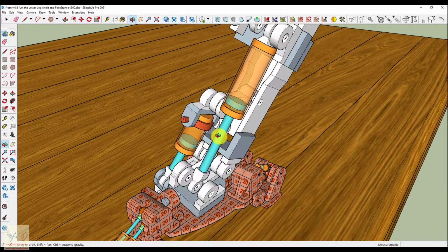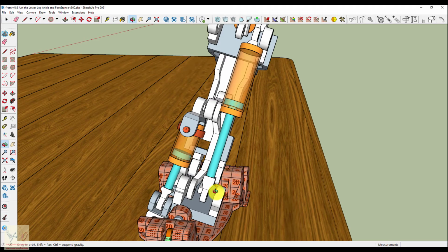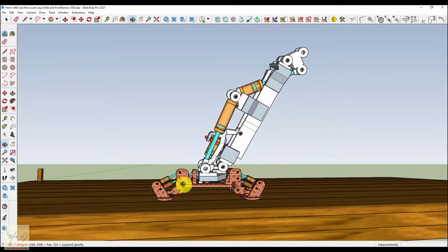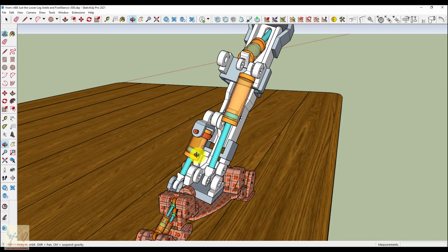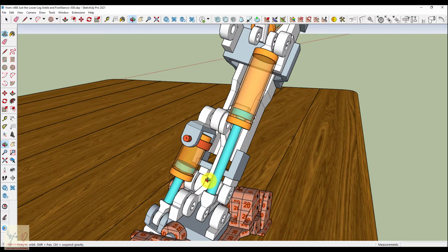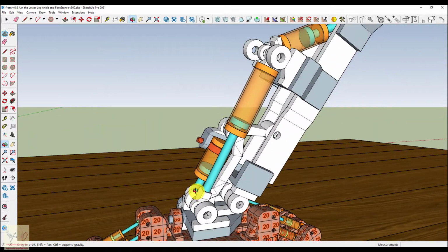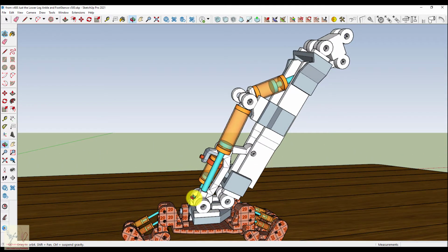And because of that, whenever you send in commands for dorsiflexion and plantar flexion, yes, they do, in fact, change the value of dorsiflexion and plantar flexion. But since the eversion inversion piston has been indexed by this linkage, the value of eversion and inversion does not change, even though dorsiflexion and plantar flexion did change.